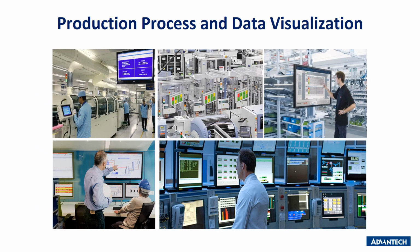Visualization is to generate clear information for the process to humans. A different layer of operator may need to check different information, and the managed layer also needs integrated data for making decisions. Users can use a PC-based programming language to develop specific user interfaces and dashboards in Windows form or web form. Non-programmers can use HMI or SCADA software to generate the same. The visualization display can show a kind of digital twin, process layout, key monitoring information table, or managed key index.